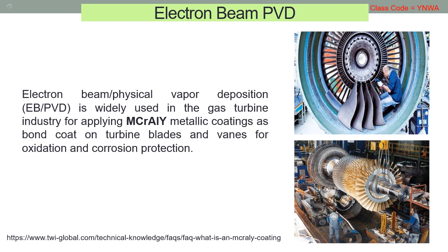Where directional solidification and single crystal production developments improved creep and fatigue resistance, TBC also improved corrosion and oxidation resistance, both of which became greater concerns as temperatures increased. The first TBC, applied in the 1970s, used an aluminide coating. Improved ceramic coatings became available in the 1980s. These coatings increased turbine blade temperature capability by about 100 degrees C. The coatings also improved blade life, almost doubling the life of turbine blades in some cases.